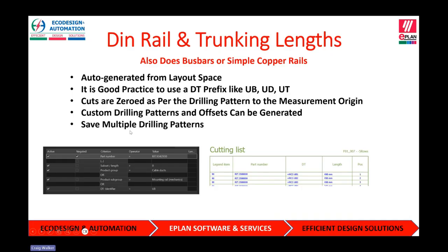And as I said, you can save multiple drilling patterns under one part and then have that part just choose which drilling pattern when you place it. This can be beneficial for something that's either mounted on its side or on its front, like a light ballast, for instance.